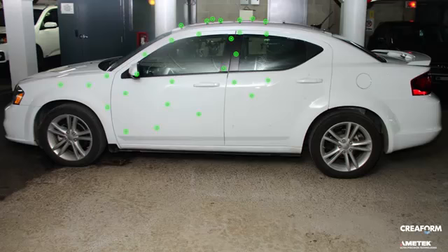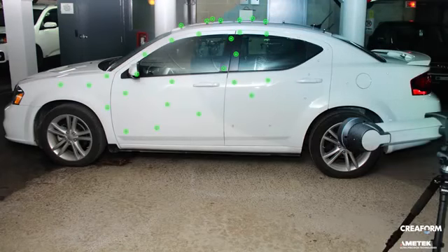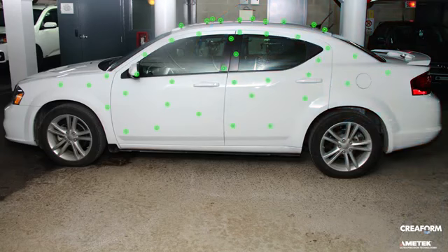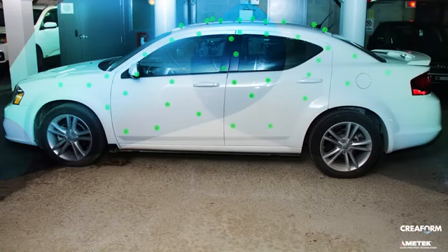To do so, you just need to add a reflective target in the new area that needs to be measured, and then add this target into the existing referential. By doing this, the volume is extended very quickly and we are still in the dynamic mode. But of course, there needs to be a certain overlap between the initial position and the new position.